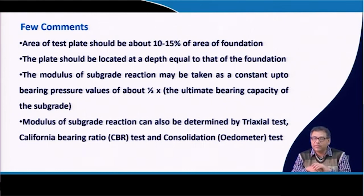Remember that. If it is a surface test, then the depth of foundation is equal to the depth of footing where you place your foundation. But if the plate load test is done at a certain depth, but less than the depth of foundation, then the depth of foundation in the equation given in the depth correction factor will be the difference between the depth of foundation and the depth of plate. Clear?